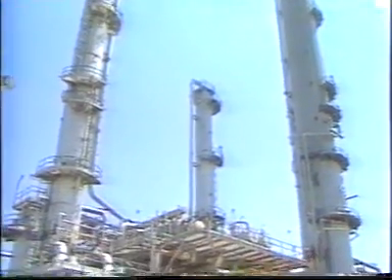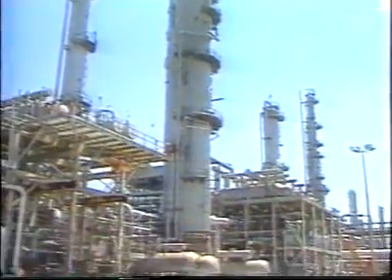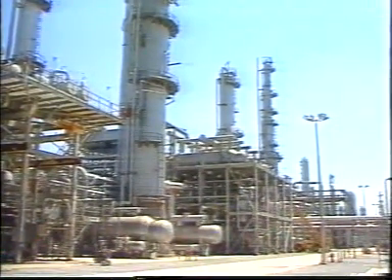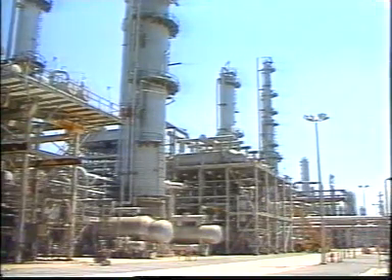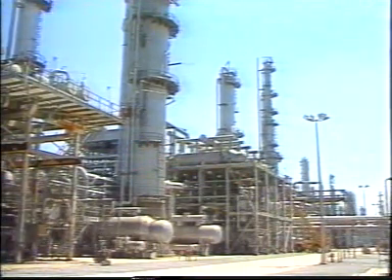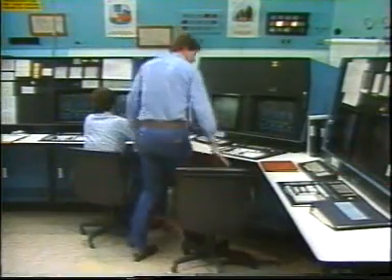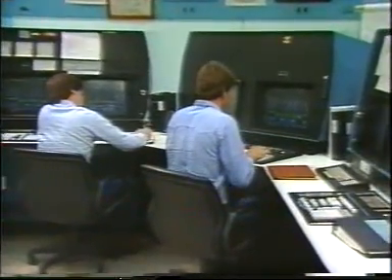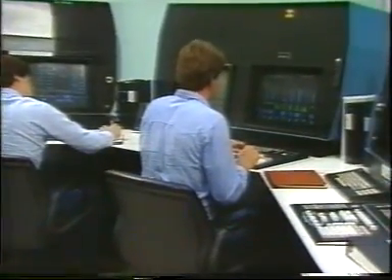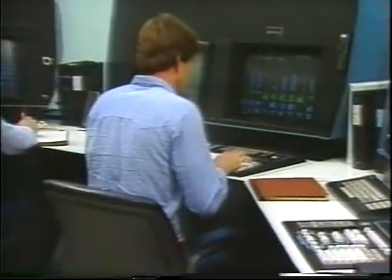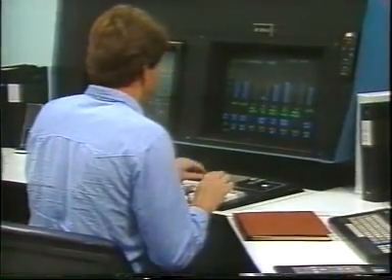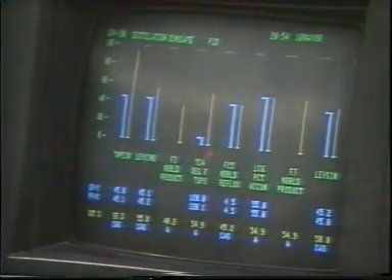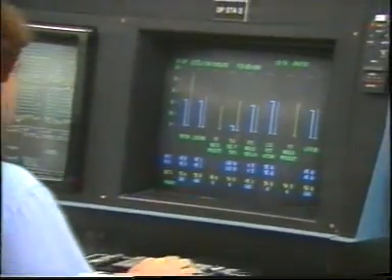In any refinery or chemical plant, there are many different kinds of distillation columns that produce a variety of products. While these towers may be designed differently and may operate under different conditions, the purpose of each tower is the same: to produce quality products that meet specifications. You learned in the program that when products are off specification, an operating change must be made to bring the products back on spec. This is usually done by adjusting the heat balance inside the column. If we change the amount of heat that is put into or taken out of a distillation column, both product composition and quantity are affected.